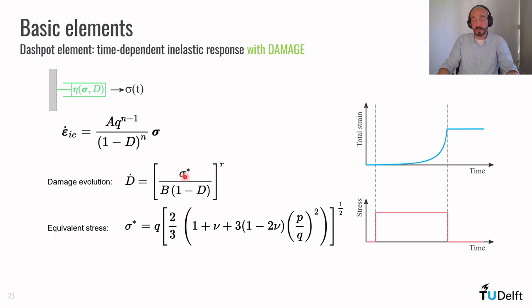If the stress is well behaved, I'm sure we can also come up with an analytical solution for that specific stress condition. But for a general stress, it's hard to solve this equation analytically. It's better to solve this equation in a numerical way, and we can do that using Newton-Raphson, and I'm going to show how to do this now.